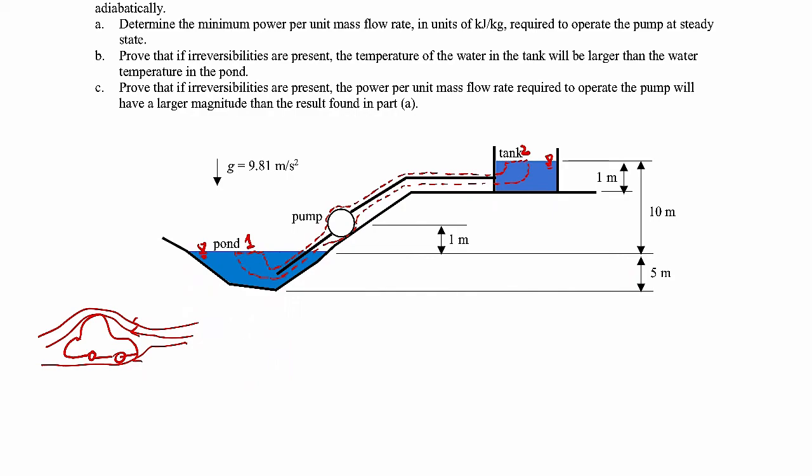You'll do a lot of this sort of thing in a fluid mechanics course, but I'm just giving you a little preview here. The other thing that I'll do right at the start is apply conservation of mass to this control volume. What you'll find is that the mass flow rate at 1 is equal to the mass flow rate at 2, just from conservation of mass. We know that if it's steady, with one inlet and one outlet, the mass flow rate in has to equal the mass flow rate out.